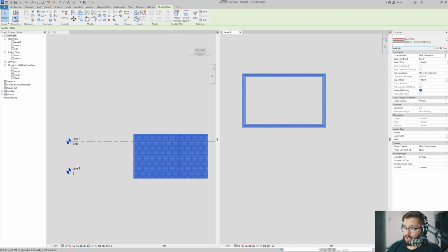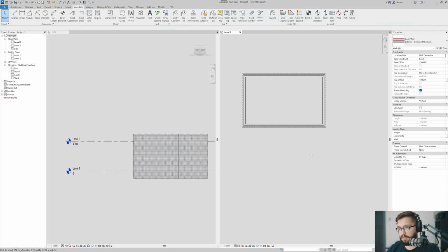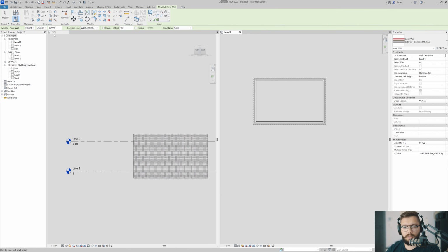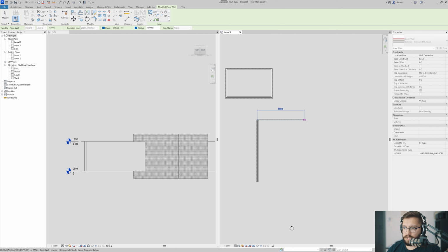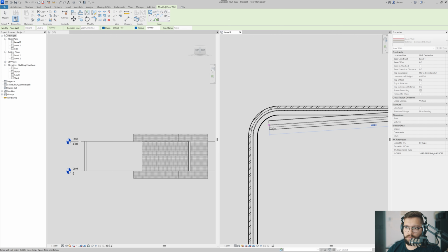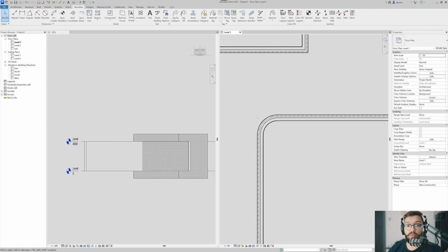These settings that we're looking at here inside the properties are actually available to you within the creation of a wall. So if I do WA again, and if I look here at my ribbon, I can already say, hey, I want this to be a height. I want it to be up to level 2, and I want to chain it because I'm going to be creating several of them. My location line coming in a second. And if I have any particular offsets or radius. Radius is a funny one because I can create a corner and it would round it for me in this way. So if this is your cup of tea, you can do it right away while you are drawing, okay?